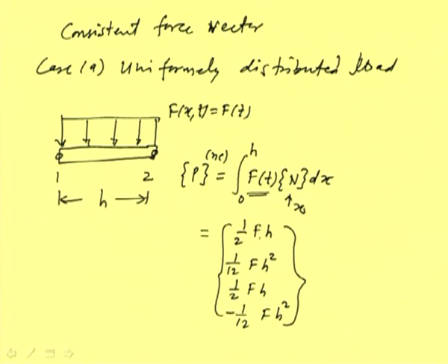So this is the consistent force vector when distributed load is there. You can see that these correspond to the forces and those correspond to the moments. These are forces and these are moments, as we had in the internal load also. These were the shear forces and these were the moments.